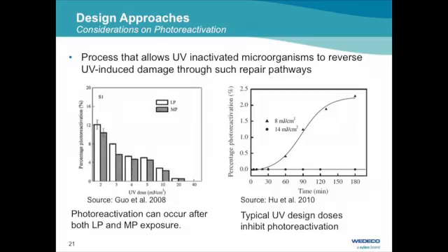And this has also been proven by another study which has been conducted, where you see here you can lose about 2 logs of your inactivation if you only apply a dose of 8 millijoules. But if you go to a dose of 40 millijoules, then it's more or less 0. So there cannot be any photoreactivation considered. And I think also during these real-life tests, we also know that there is no photoreactivation observed.